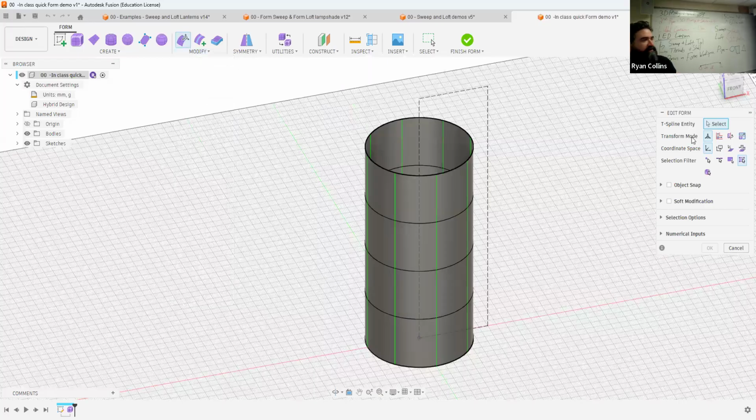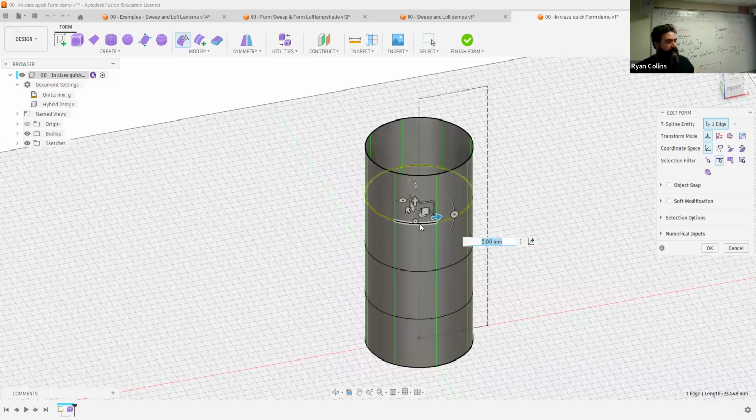And there's so many things here, but we're going to select. There's all these different things. Don't worry about those right now. Your selection filter will allow you to select by vertice, which is where any of those faces or any of those edge lines connect, by the edge lines themselves, or by the faces. So I can only select the edge lines here, or by faces, I can only select the big old faces. We're going to ignore any of those. I'm just going to use the edges for now. So if I select, let's say, that one by double click, or I can just select the one and the symmetry is going to keep me on task there.